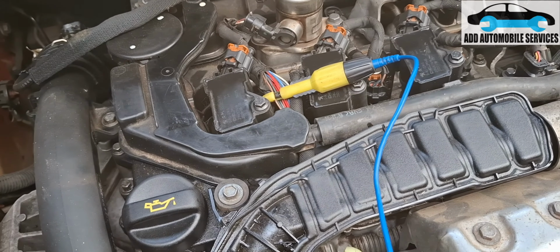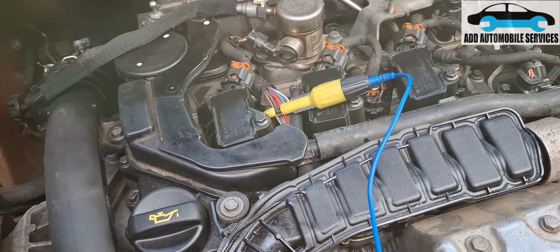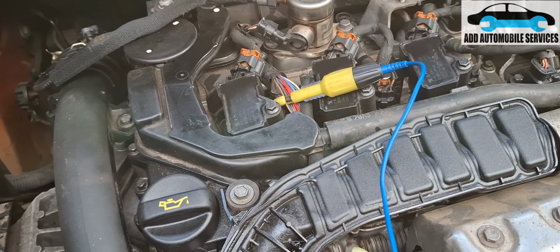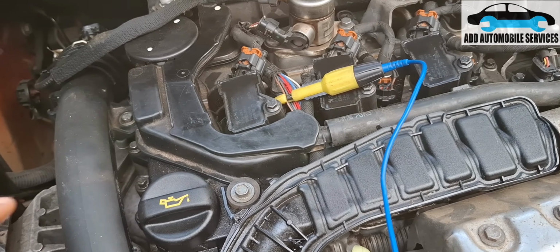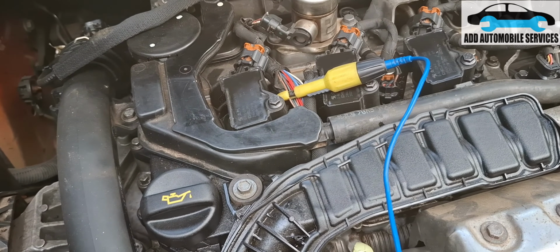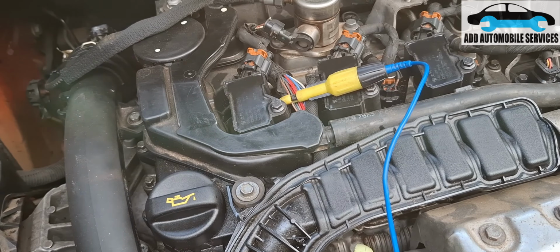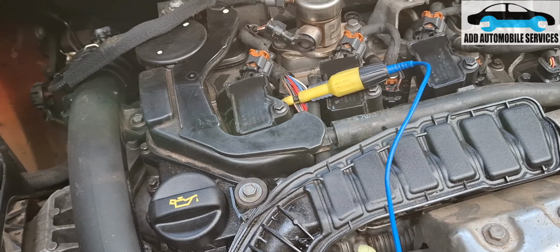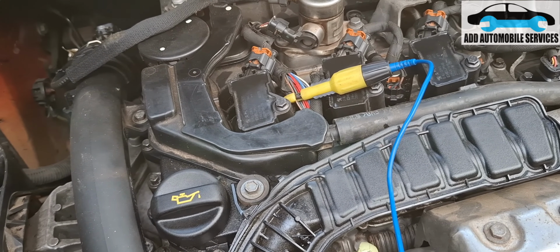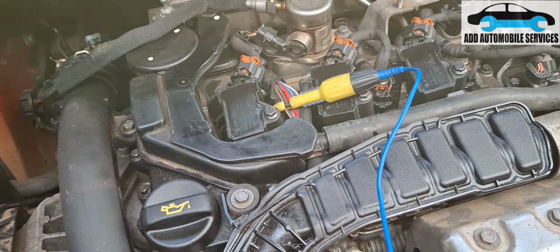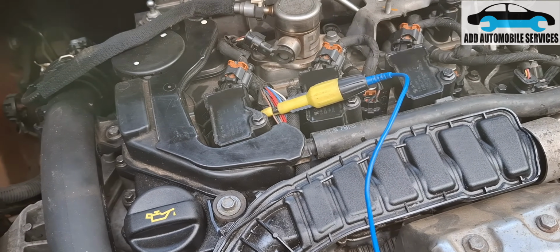Now I have 1 power and 1 signal line, so I'm searching for the ground. If I test the other one and it is not ground and it is also power, then of the 2 wires supplying power, one has to be ground. Because I don't have the wiring diagram, I have to cut one and hope that will be my ground. So let me do that and bring you guys back.